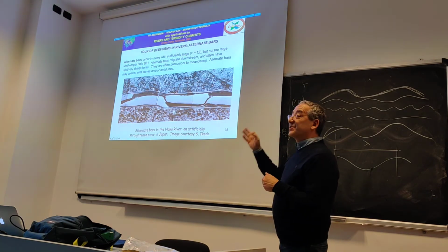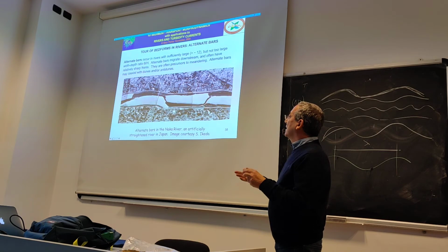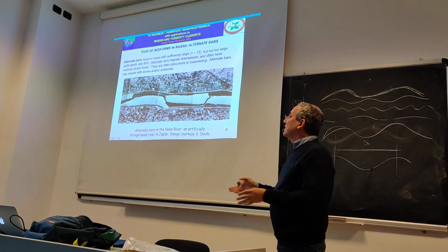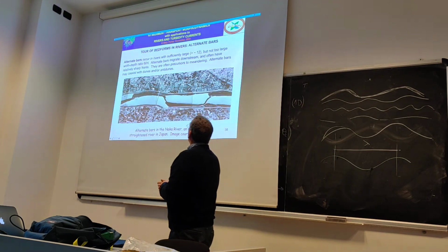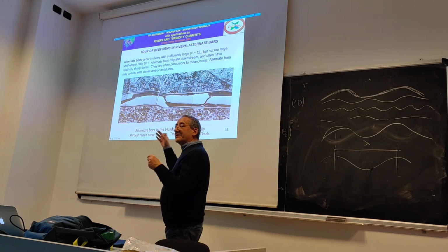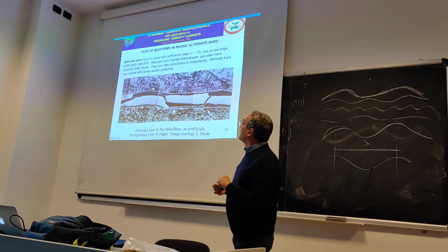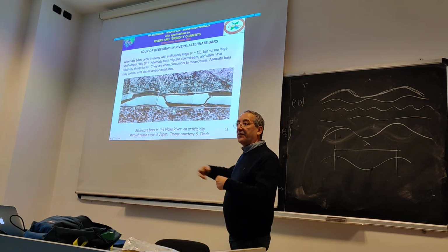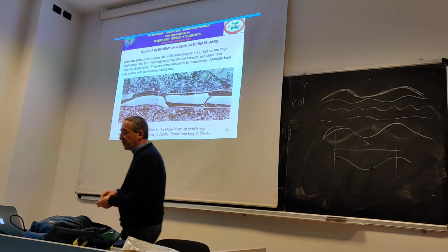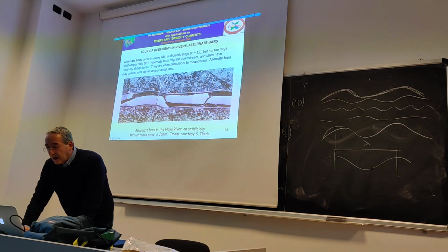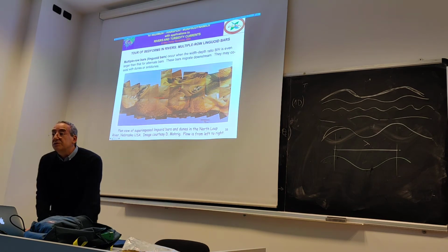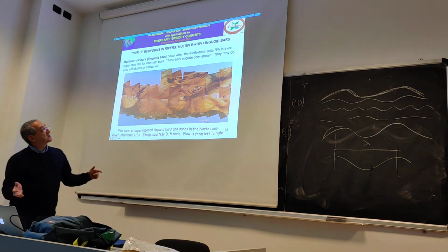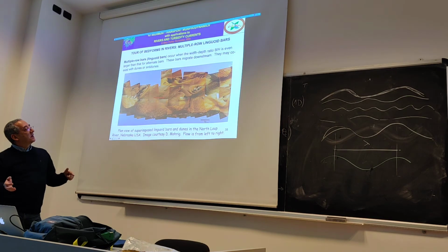So you typically observe natural alternate bars only when the river has been straightened artificially, because sooner or later they will lead to the formation of meanders if the river is free to evolve. And alternate bars are just the first mode, the first transverse mode of instability.